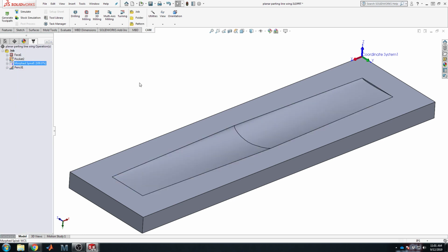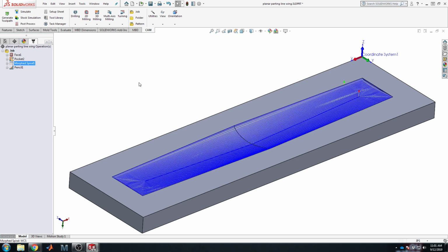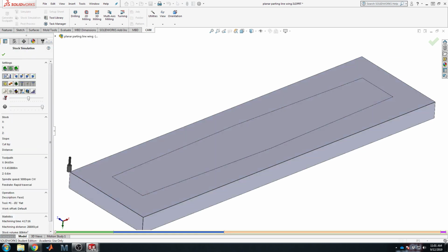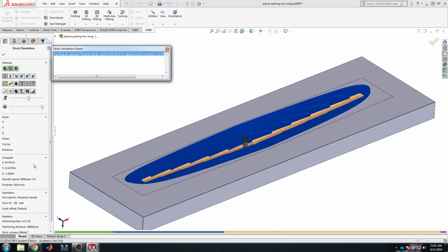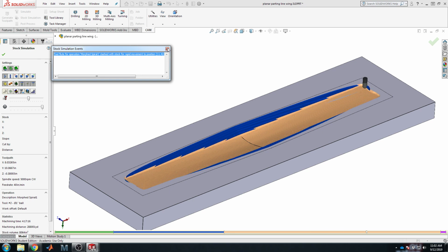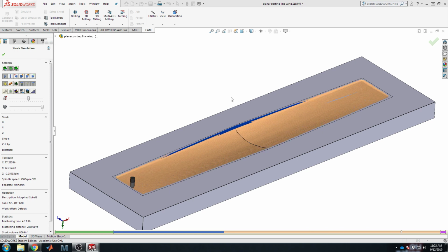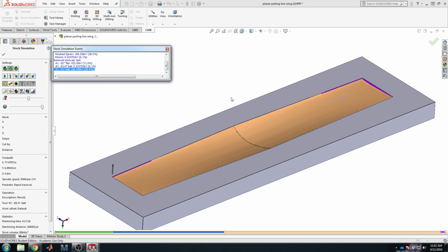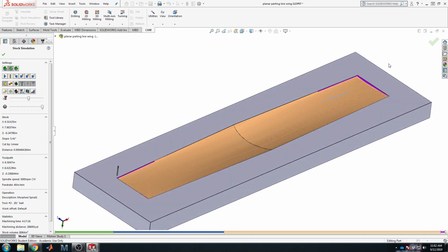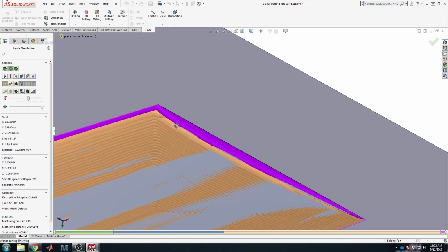So this would be a nice compromise between cutting time and cutting accuracy, the amount of curvature we can adhere to. So obviously the path was longer. If we simulate the whole job, this would now be at probably 5-6 hours. So you have 4 hours, 17 minutes. So we added an hour of time over the 2-inch ball option.